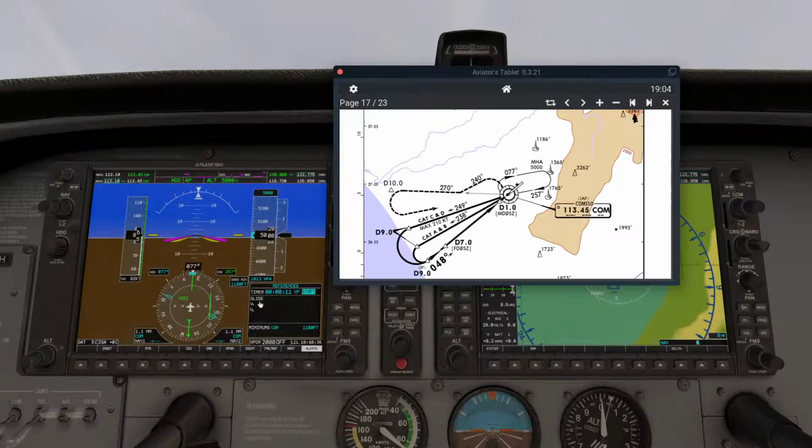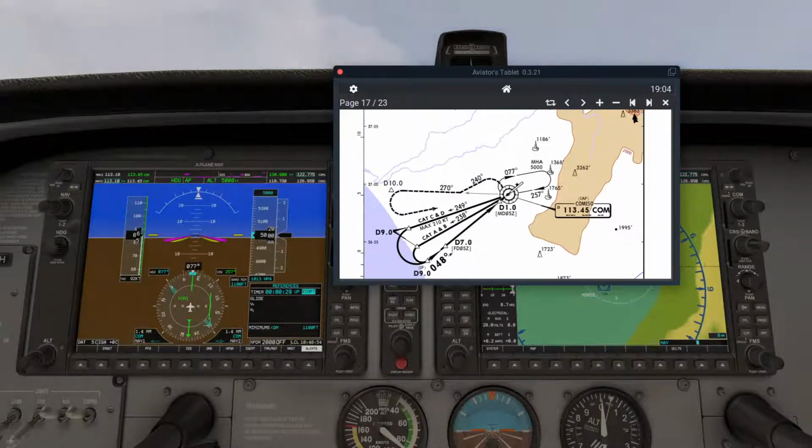We will continue for 1 minute and then turn right again. Turn right again on course 257 to complete the holding. Actually, the holding entry is completed, and we are entering the holding right now on 077 heading for the outbound leg of the holding.